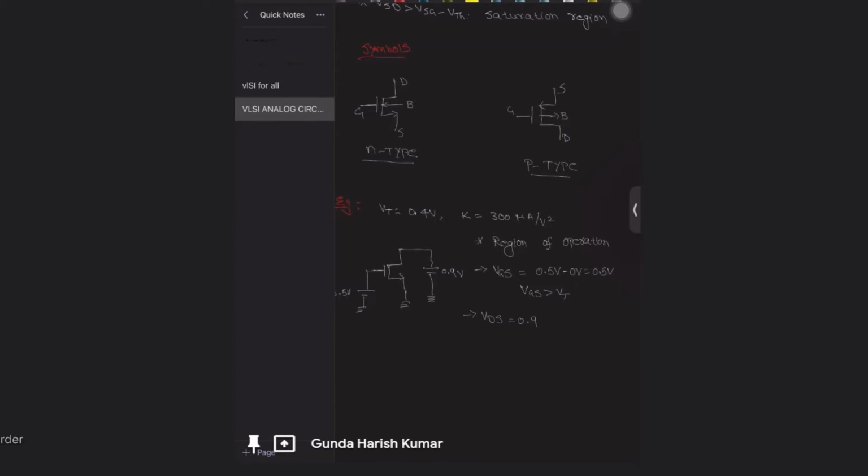Now VDS is 0.9, which is greater than VGS minus VT. So 0.9 greater than VGS, that is 0.5 minus 0.4. So 0.9 greater than 0.1.